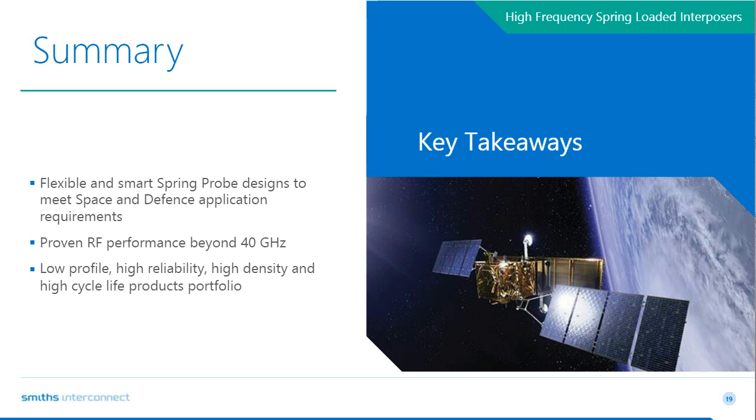That's why the solderless approach is the most popular for us, to avoid contaminating the connector and to allow for ease of rework and ease of maintenance in the field. So the best way to handle it would be to cap it off securely, so that you don't allow ingress of contamination into the connector.